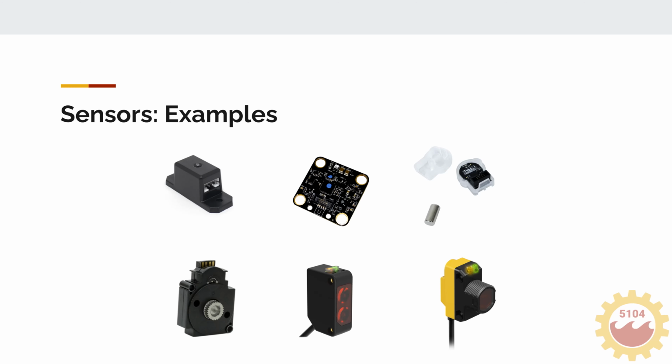This is super simple on low torque mechanisms. For example, our control panel mechanism had this. There's not much force against it, and so it's super good. The thing about VersaPlanetary things and other sorts is this gear right here can shred if you're under high torque. So I don't recommend it for an elevator or a big arm like to climb.